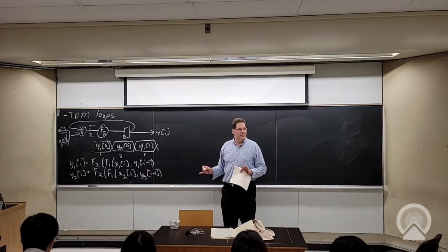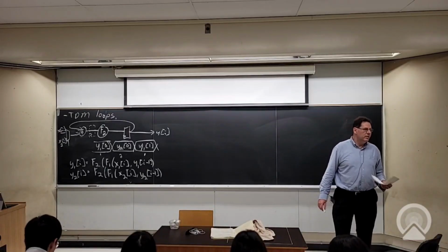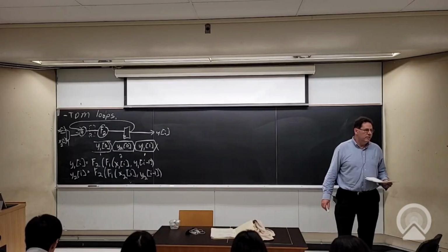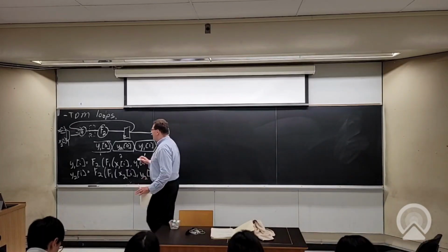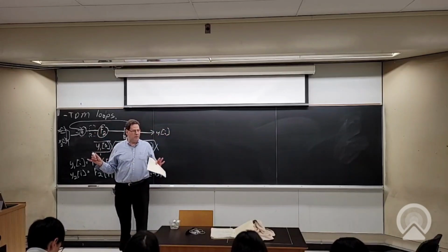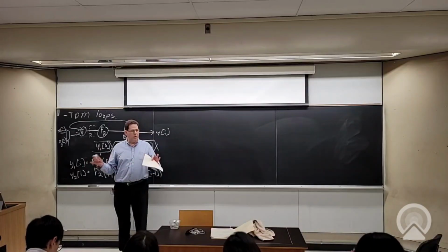So does this make sense? Yeah. Just as a general rule of thumb, the amount of registers you have on the loop is how many streams you need to multiplex. Essentially this optimization starts from a design that works. Say you wrote a finite state machine, and it works on one stream.